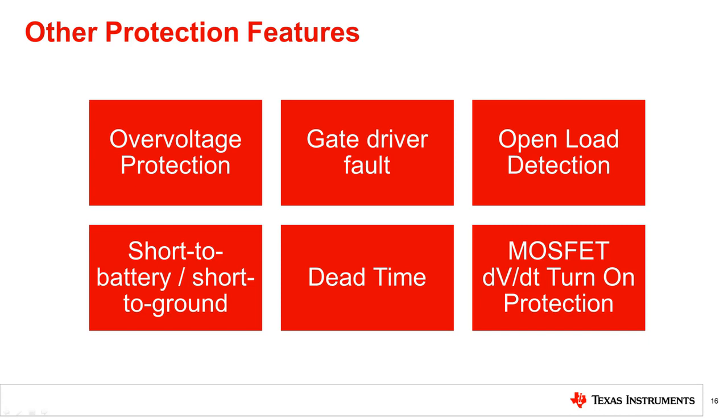By not detecting a change in a period of time, this can detect output shorts on the gate drive pins. Open load detection is a feature that sends a fault when the load is disconnected from the output stages of the MOSFETs. Offline short to battery and short to ground diagnostics are available on devices to detect shorts on external components before the motor starts to spin.